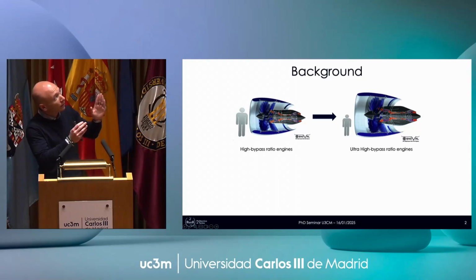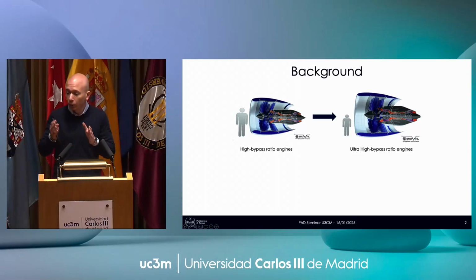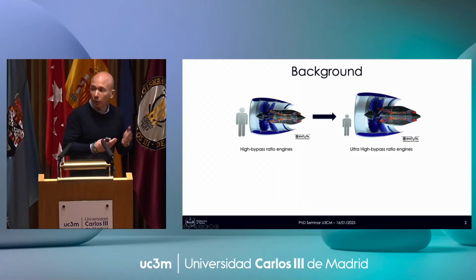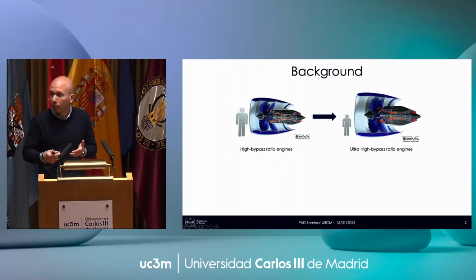Similarly, the distance between the engines, as you can see, is getting shorter. And the distance between the rotor and the stator is decreasing. Then there is more interaction between the wake of the rotor and the stator, and then we have another source of noise, which is broadband.